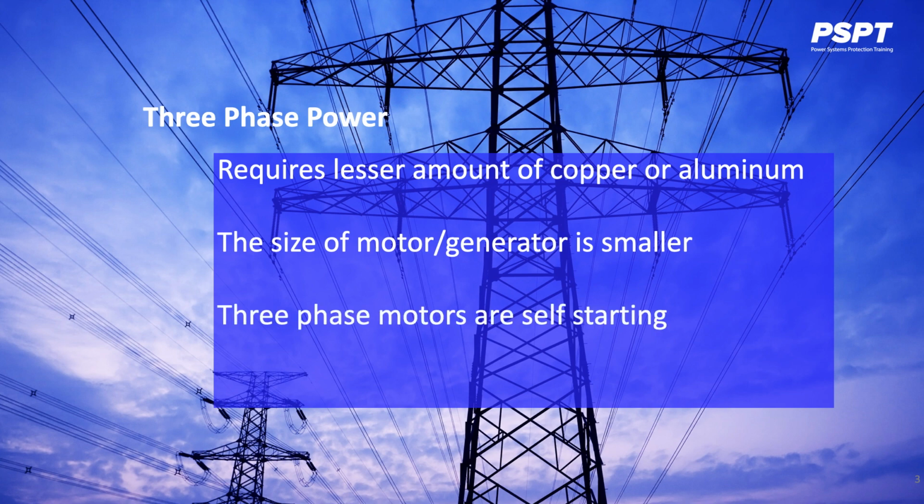Three-phase motors are self-starting as they can produce a rotating magnetic field. The single-phase motor requires special starting windings as it produces only a pulsing magnetic field. In single-phase motors, the power transferred in motors is a function of instantaneous current, which is constantly varying. Hence, single-phase motors are more prone to vibrations, whereas in three-phase motors, the power transferred is much smoother and much more uniform throughout the cycle. Hence, there's fewer vibrations to be concerned about.